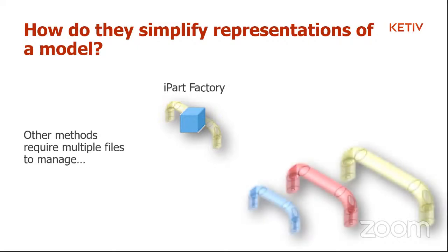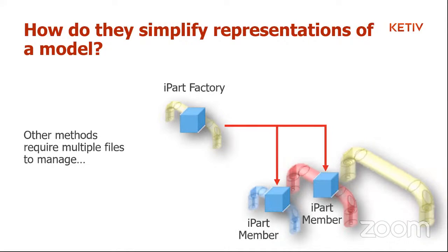So for example, if you wanted to create larger versions of this handle, different color versions of this handle, handles with different machining features, etc., you're going to create a table that defines each one of those uniquely. And at some point, you're going to have to generate an iPart member. The process is the same, really, if you're going to derive a component. You're going to create a base component and derive it kind of like you would the iPart members.